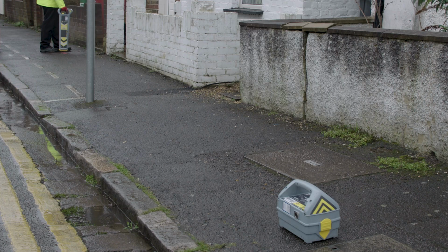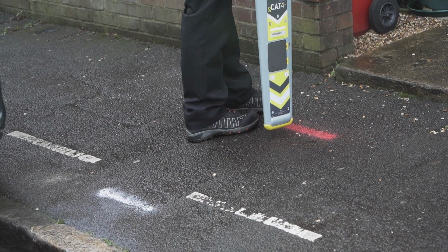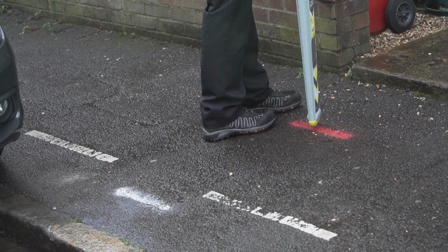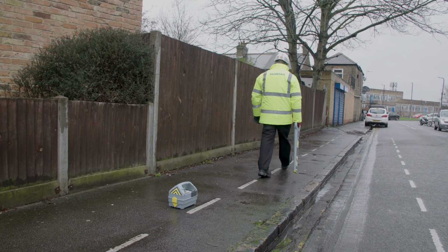Please note that attempting this induction mode can often lead to mistakes, as the signal usually travels along the better conductor in the footpath, which is usually the power cable rather than the comms cable, whereas with clamp you are more likely to locate the comms. Place the Genny 10 meters away from where you intend to scan with the CAT.